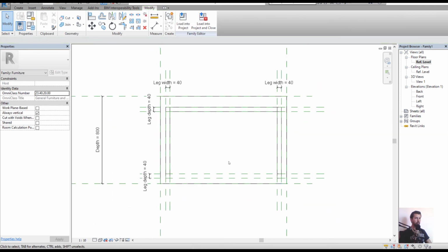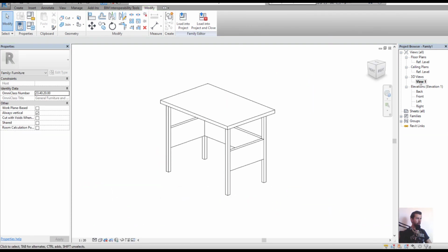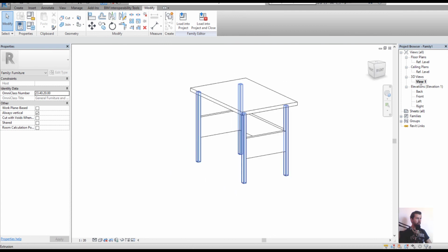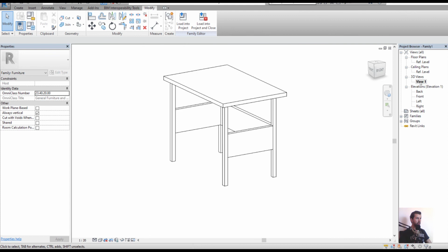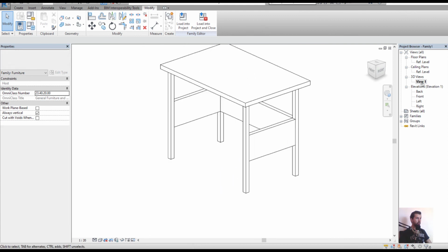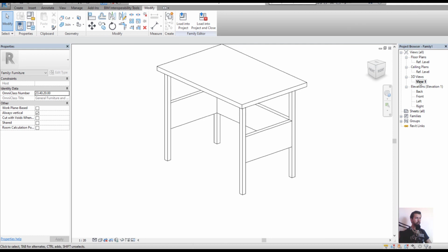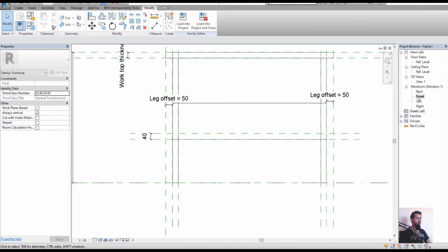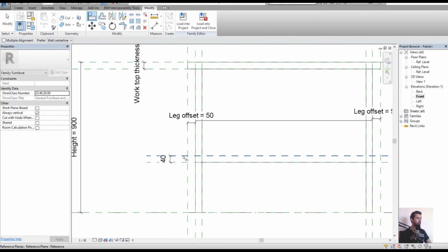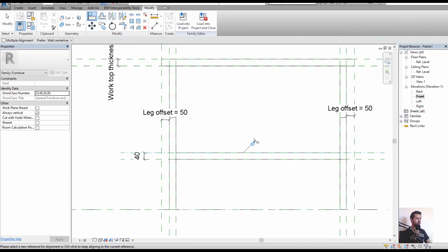And let's go to 3D view and look how our table looks like. As you can see, it is extruded at 250, but on that reference plane that we created and set from there. So we're gonna go to the front and we're gonna lock that as well, which is fine. We can do that. Alignment, reference plane, the top one, and you click on that and lock.